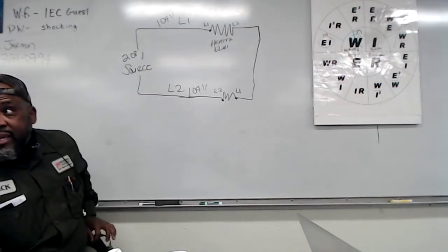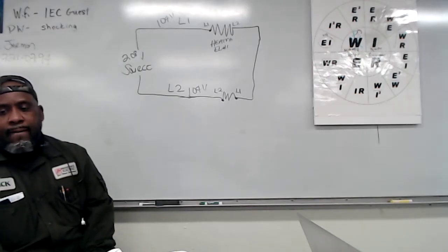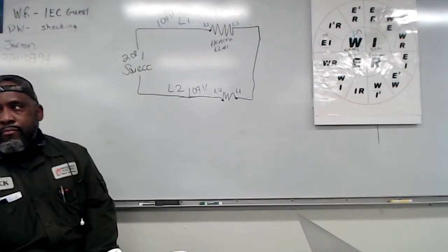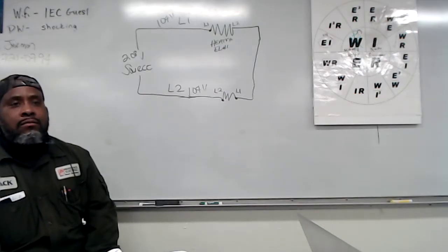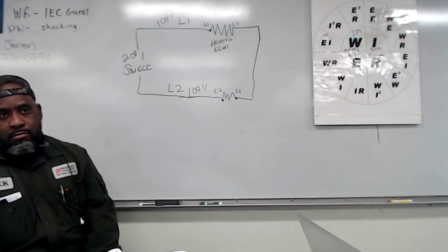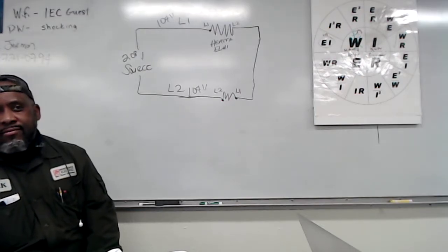We're just talking about what we got right now. Okay? How is it putting off 208 through one wire on a 2-pole breaker? It's putting out 208 together. But each lead would be 104. Yes. One lead to ground will be 104.